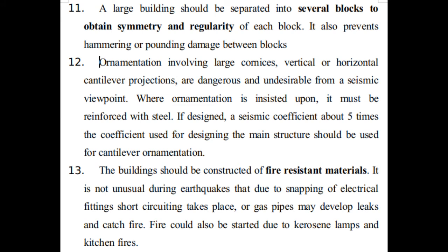Point number 13. The building should be constructed of fire resistant materials. Why? Because it is not unusual during the earthquake that due to the snapping of the electrical fittings, short circuiting takes place, or gas pipes may develop leaks and catch fire. Fire could also be started due to the kerosene lamps or the kitchen fires. So while designing the building, you should also consider fire resistant materials.